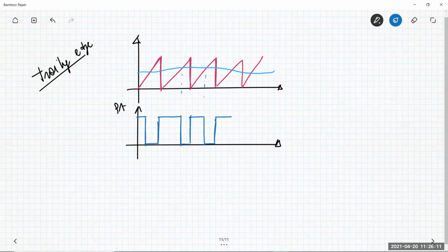If you look at how QA is generated, you can see that you have something like this. So there is the possibility to modulate the width of the pulses, of course, because it's the basis of the pulse width modulation process, but you are modulating just the falling edge, because the rising edge is fixed, as the sawtooth is instantaneous in this action.